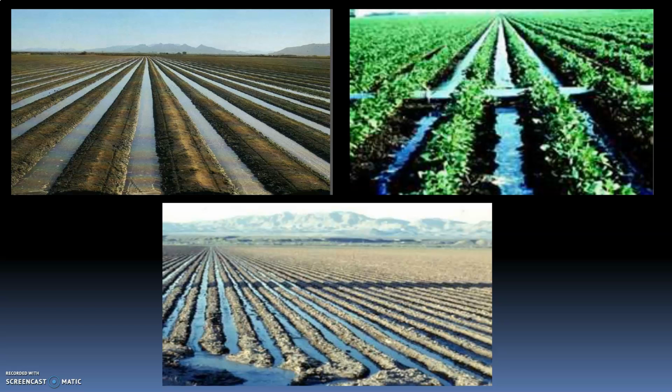Instead of distributing the water evenly throughout the whole field, these narrow channels are dug out. And these furrows must all have equal dimensions. This you have to note down. These furrows have to be made of equal dimensions in order to guarantee that the water is distributed evenly.